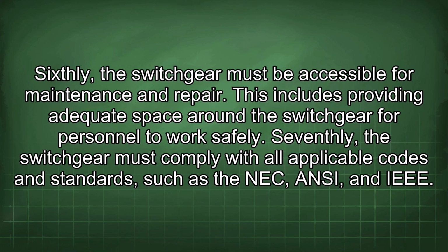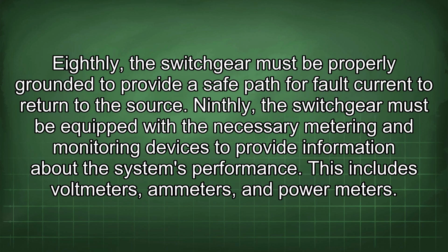Sixthly, the switchgear must be accessible for maintenance and repair. This includes providing adequate space around the switchgear for personnel to work safely. Seventhly, the switchgear must comply with all applicable codes and standards such as the NEC, ANSI, and IEEE. Eighthly, the switchgear must be properly grounded to provide a safe path for fault current to return to the source.